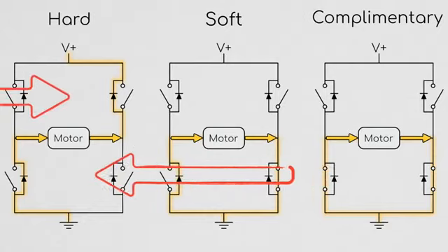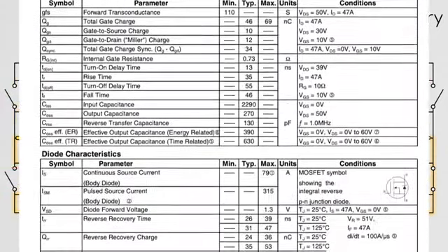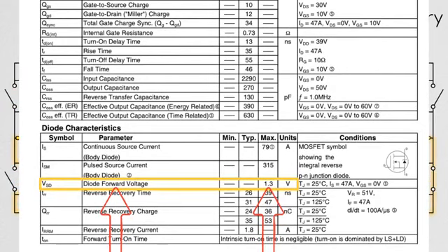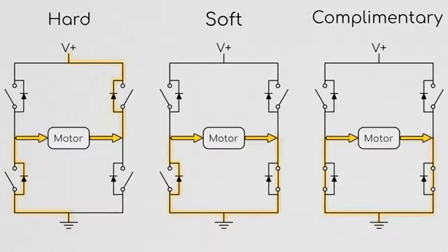Meanwhile, during hard switching, we flow through two diodes. In practice, the drops across these diodes are often over a volt each. For lower voltage systems, this can be huge and can cause current to decay much faster than it otherwise would. Essentially, while the current will continue to flow during the unforced phase of soft switching, it will have about a volt pushing back on it due to the diode drop.